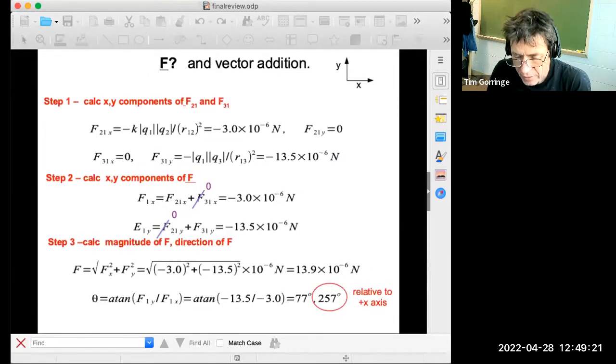Okay, so here we go. This is a problem of adding the two force vectors. And when you want to add two force vectors, in general, we break the individual forces down into their components in the XY directions, horizontal and vertical. We are then able to add up all the contributions in, say, the X direction, and all the contributions in the Y direction, to get the resulting force in XY component language. And then finally, at the end, if we want the magnitude and the direction, we can convert the resulting force from the XY component language to the magnitude and direction language.